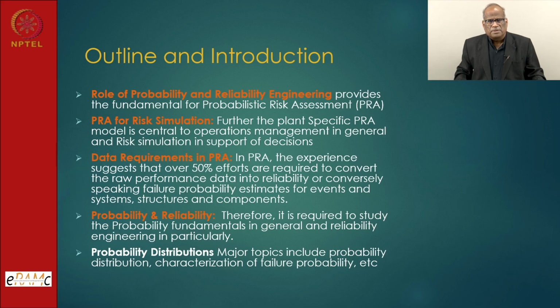It becomes all the more important in respect of human factor, because 50% of the effort goes into collecting data, including human factor data, and human factor data has a higher uncertainty. So there is an opportunity available on the simulator to integrate plant specific data on human performance with the simulator experience, and to reduce the uncertainty in the data.